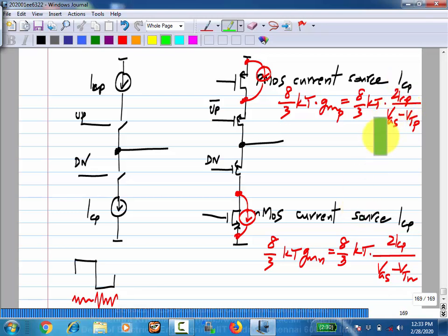Okay, so this kind of average picture is okay because this whole thing is anyway getting filtered by a low pass transfer function. Is this okay? So those things you have to do. Now doing all of that by hand when this and that have different spectral densities is possible, but it's a little messy. In the simulators, there are periodic steady state simulations which will give you the right answer. Okay?